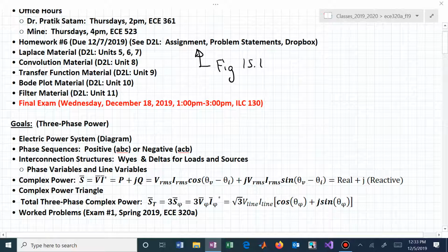That's the Q. I find it helpful to just sketch the complex power triangle. When I'm thinking about these, I just draw a triangle. The hypotenuse or Pythagorean just makes me feel warm and fuzzy, so I just draw that triangle, and then I'm more comfortable talking about P's and Q's and which direction I'm headed in terms of Q. Is it a lagging or is it a leading relationship on my voltage and current? And then we'll work through some problems. That's the idea, and I guess the step between working problems and complex power is we can up it by a factor of 3 by going to three-phase.